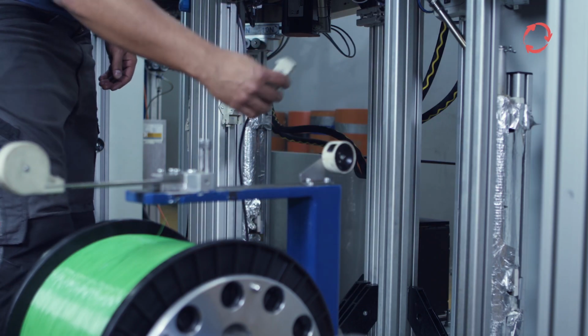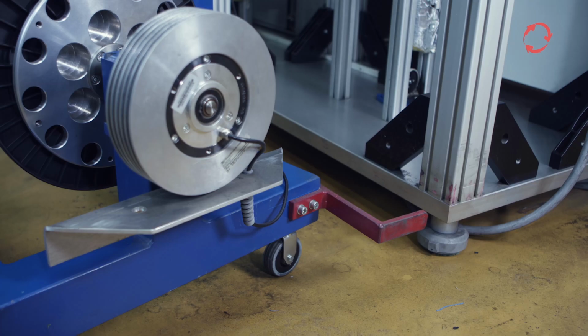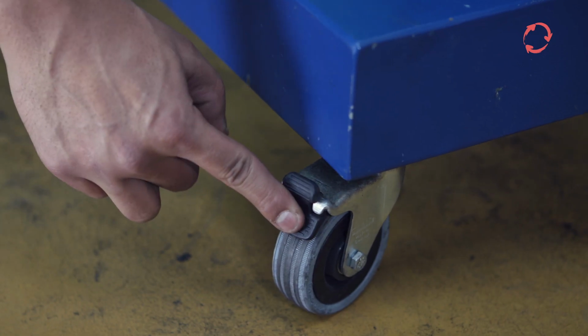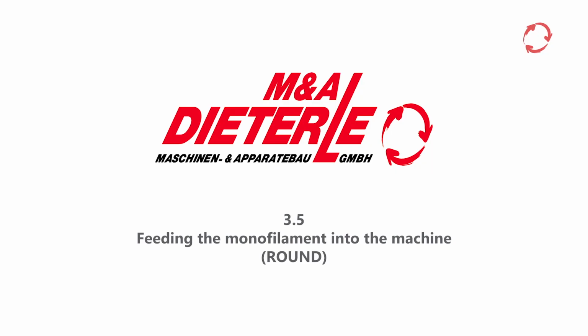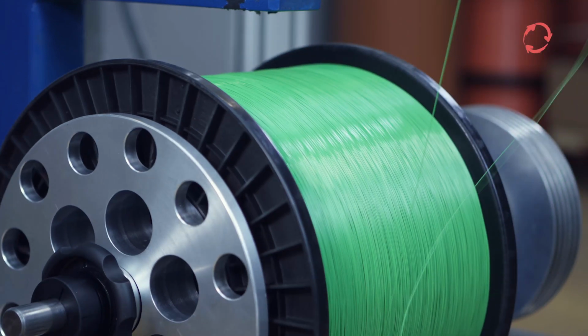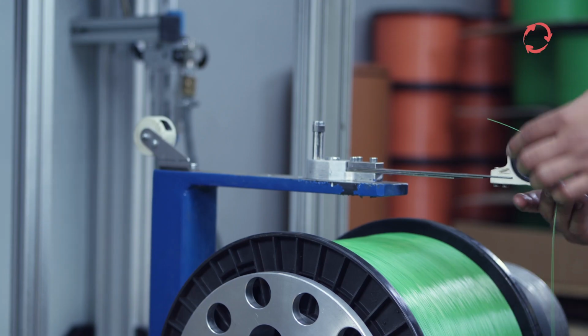Connect the connection cable of the tangential unwinder to the machine. Now slide the tangential unwinder to the machine with the appropriate angle, and finally fix the brakes of the wheels. Use scissors to cut the knot of the thread on the coil. Pull the thread from the coil and through the front deflection roller in the direction of the two guide pins.